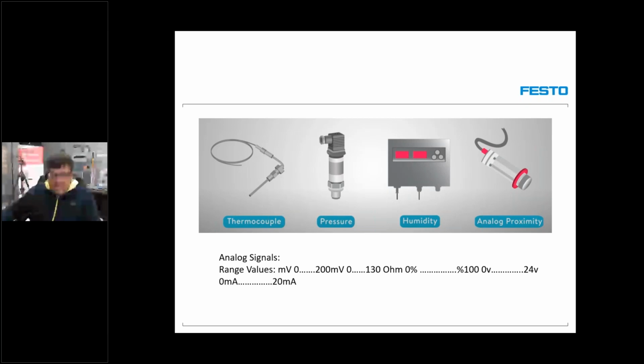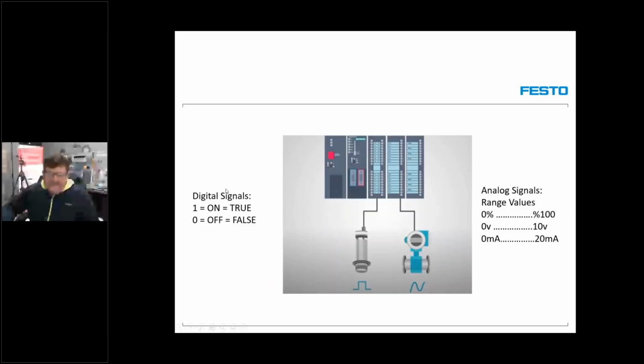So that means you have digital input signals and you have analog input signals. Guys, digital signals, in our case, for example, today we will say that there is a 1. We refer to it as a binary signal. That means when the proximity sensor senses that there is a box, for example, on my conveyor, it will send a 24 volt.